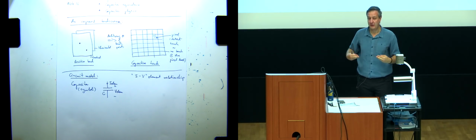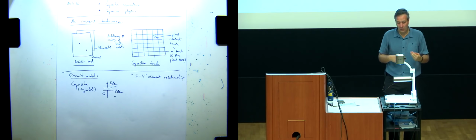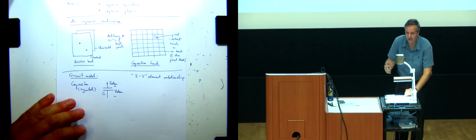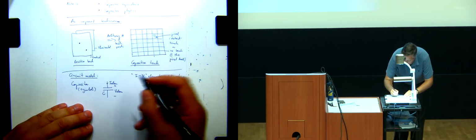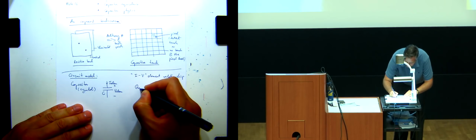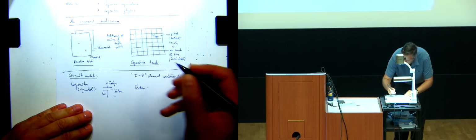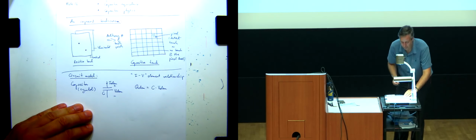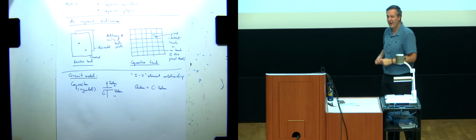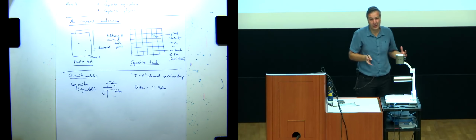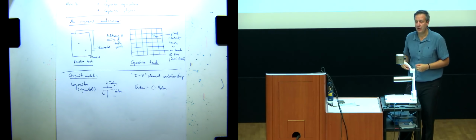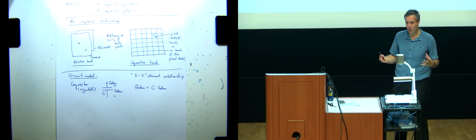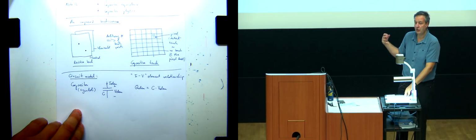we're going to sort of derive it a little bit, because what holds in terms of V for a capacitor is not that I is somehow proportional to V, but actually the charge on the element is proportional to the V element. Okay. So, in other words, you can think of a capacitor as a bucket. Current is coming in, it's bringing some charge, and the amount of that charge in that bucket, in that storage, is proportional to the voltage across it.